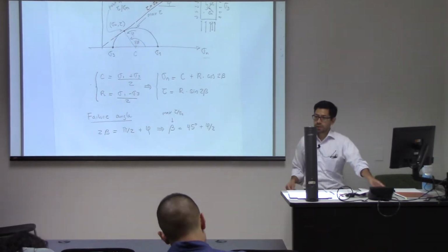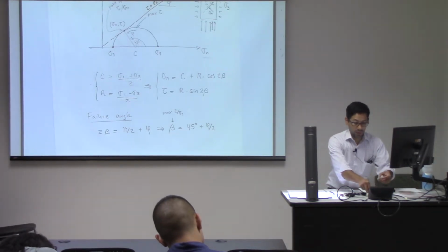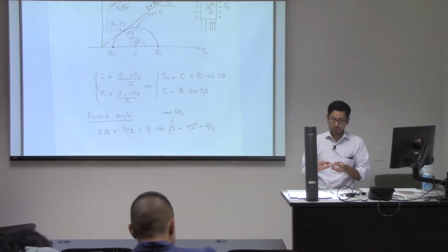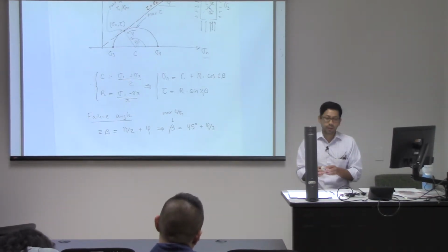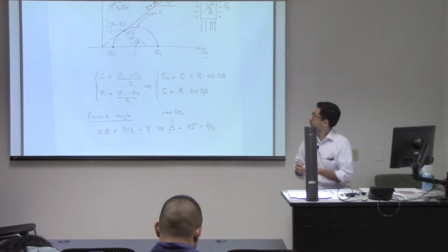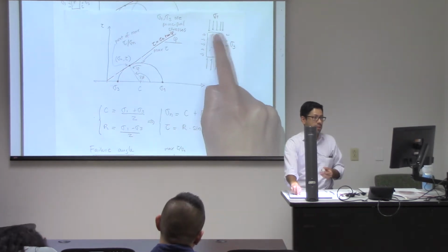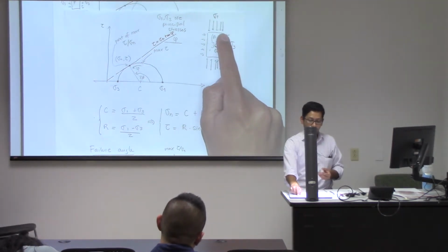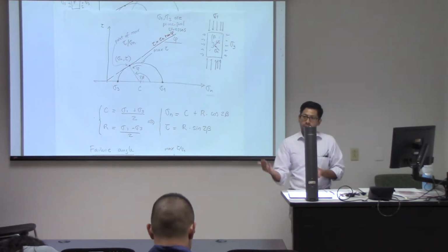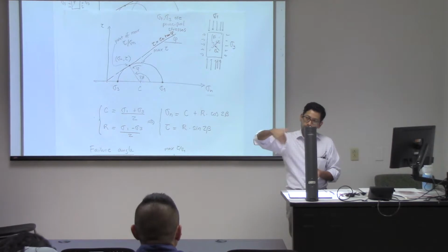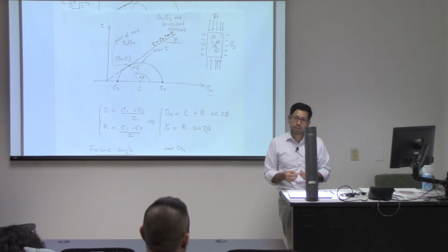You had a question, Ms. Montero. Well, like you said that these are principal stresses and there's no shear stress. So is this Mohr circle describing the shear stress inside of the circle? Yes, it's describing. We don't have shear stresses on the faces of the principal stresses, but inside it, there is actually shear stress.